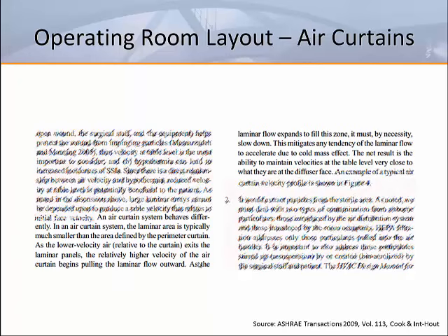The paper presented in 2009 looked at a unidirectional diffuser array on its own and a unidirectional and air curtain design. One of its findings is that the use of an air curtain with a smaller primary diffuser array mitigates the tendency of the primary diffuser array field to collapse on itself due to its cold mass effect.